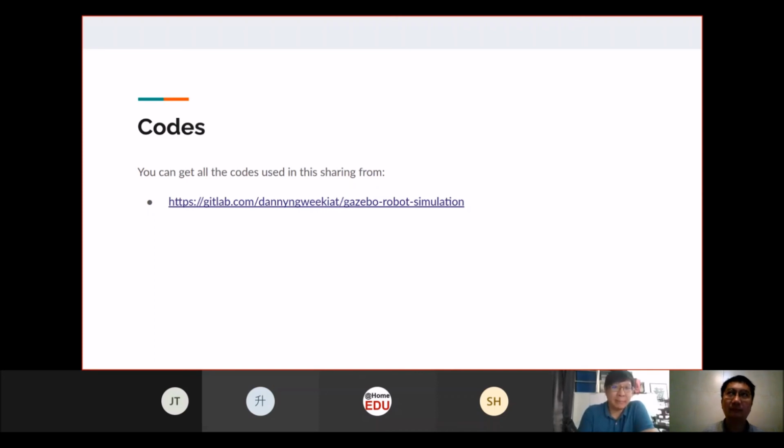That's why I'm using the SLAM toolbox. Okay. They have their own; you can run multiple times and do the map closure yourself. They have multiple matching, so the SLAM toolbox covers that for us. I'm not sure what the advantages of the SLAM toolbox are, because I heard people not using G mapping and AMCL are using, for example, Hector SLAM. Hector SLAM, Cartographer, we have tried before.